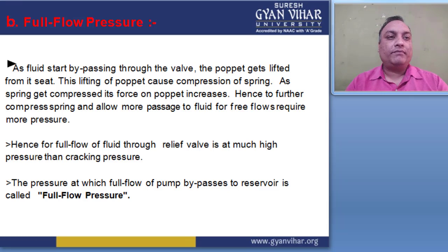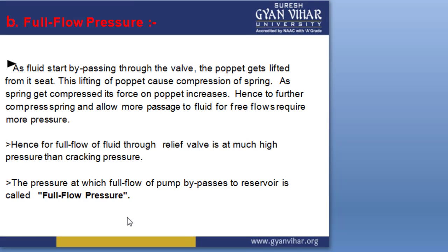At that time, the fluid flow through the relief valve is at a much higher pressure than the cracking pressure. The cracking pressure is the pressure when the valve starts to open, and at this time the valve is fully open. The pressure at which the full flow of the pump bypasses to the reservoir is called the full flow pressure.